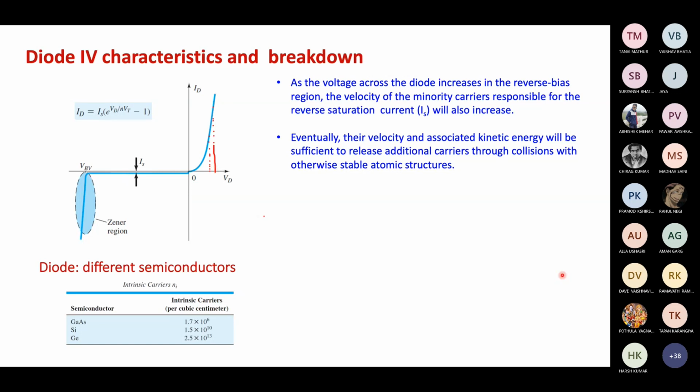And before this voltage, there is not so significant current in the diode, and especially for the lower voltages, the diode is almost off. And even for negative voltages, the diode is almost off, because this IS current is a very small current. It is just a few microamperes. And this forward current is in milliamperes. It's a large current.